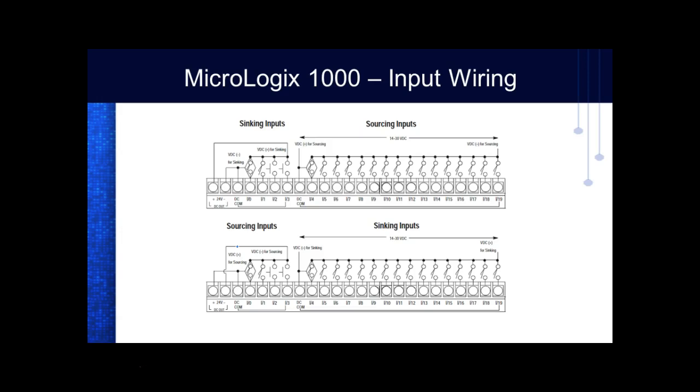Now normally it lets you, when we go to the outputs on the 1100, you got access to every one of them because they're relay. If they're relay outputs, then you determine if they're sinking and sourcing. The Siemens that I've seen that uses relay outputs use groups. They use groups. But Allen Bradley, when we go to the outputs, so here they got these set up for sinking.